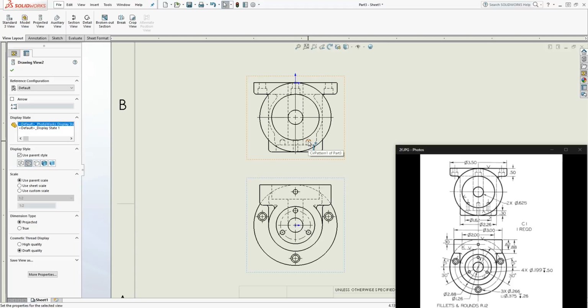The only thing that you can feel free to check on is this over here. You can't really go by the representation too much because you can see that hole is sticking in there, but it is 0.5. So is it 0.5 from this face, or is it 0.5 from this face? But I'm pretty sure, since it is 4 holes and the first one is starting from the face outside, that's letting me know it is 0.5 from that face back.